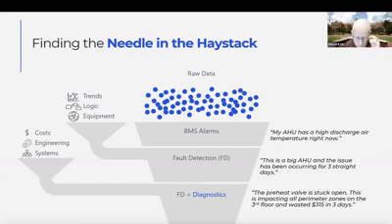So you have lots of data coming in, different data points telling you temperatures, valve positions, damper positions, and all that information comes in, and your BMS then tells the building what to do and will sometimes alarm if something is far out of range to the point where it needs a quick response. An example of that would be your air handling unit is discharging a very high temperature right now, and that's all you know about it. Fault detection will give you another layer of information.